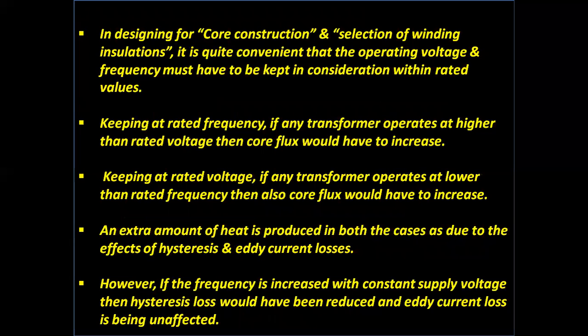In designing the core construction and selecting winding insulations, it is convenient that the operating voltage and frequency be kept within rated values. Keeping at rated frequency, if any transformer operates at higher than rated voltage, then core flux will increase. Similarly, keeping at rated voltage, if any transformer operates at lower than rated frequency, then also core flux will increase.